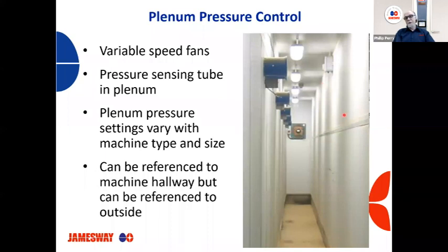Here we have a picture of a hatcher plenum. We have one fan extracting the air out of the plenum area. These are some P30s or P20s, and these just have a damper system. They don't have the fan. So as the air is being moved through the hatcher, it is pulled into here, and this fan will extract that air, and it modulates depending on the amount of stale air being dumped into the plenum area.